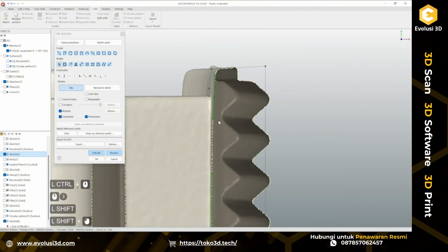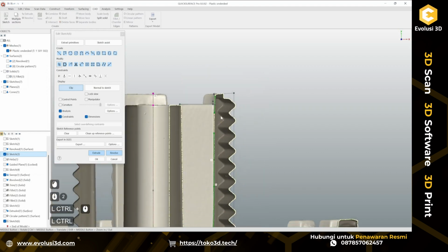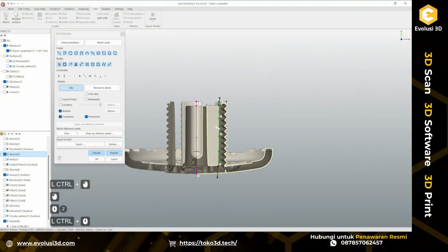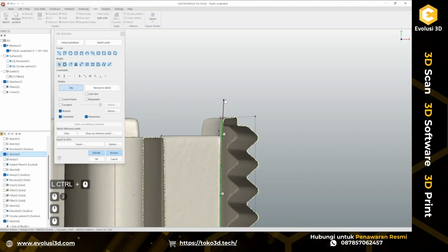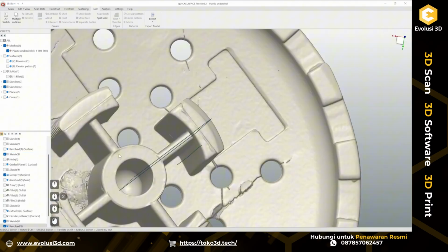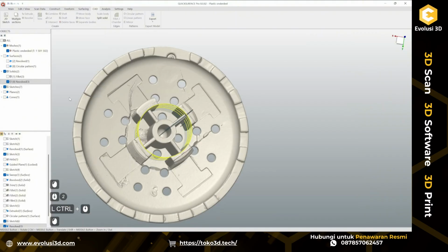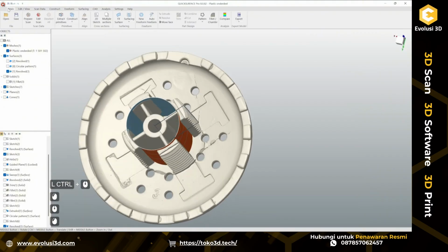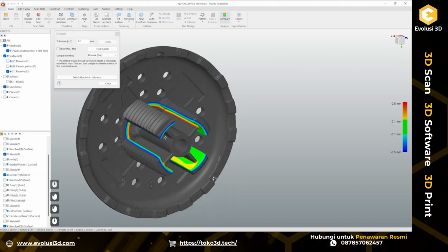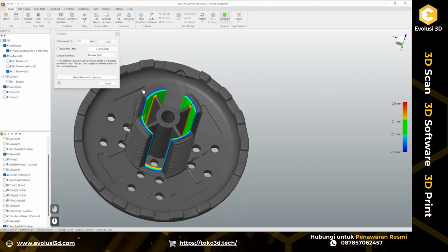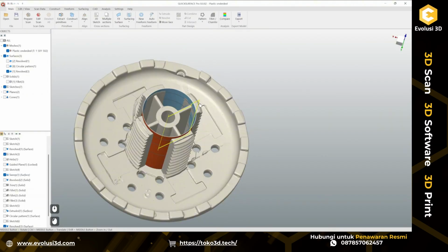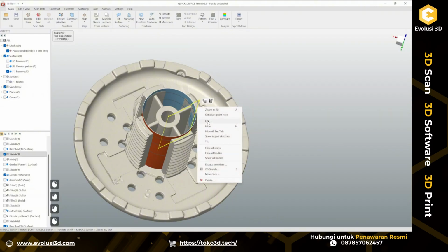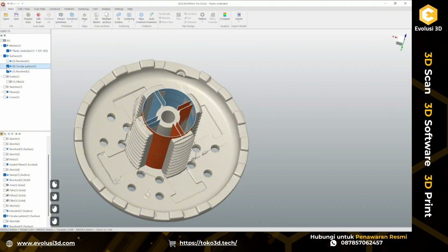So let's fit another line here. Intersect, extend this side slightly. Let's add some radius here as well. Okay, like this, and now I can do revolve. And let's verify. Yep, looks good. Okay, so for now I'm going to hide this sketch, unhide my circular pattern, and unhide my cone.